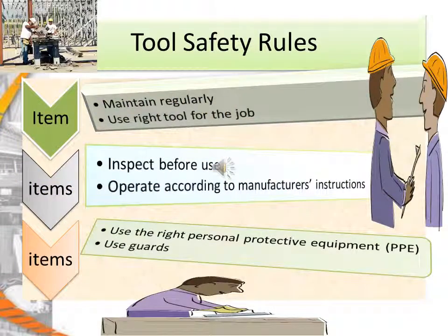Tool safety rules. Maintain them regularly, use the right tool for the job, inspect them before use according to manufacturer specifications. Operate them according to the same instructions. Use the right personal protective equipment and always use the guards.